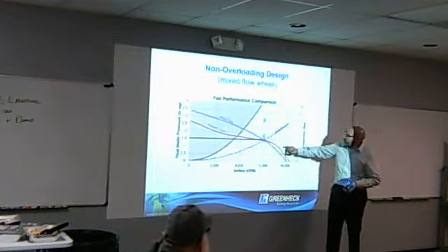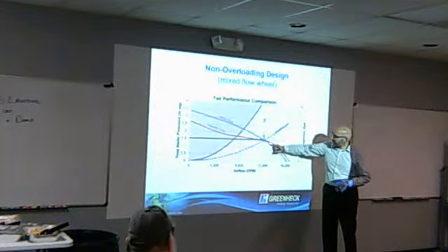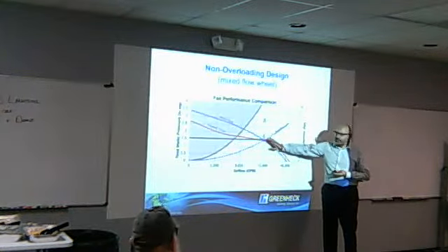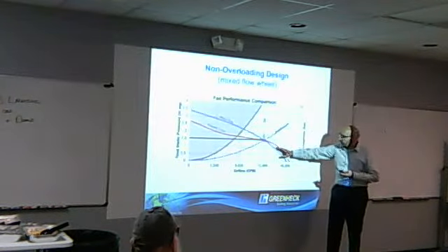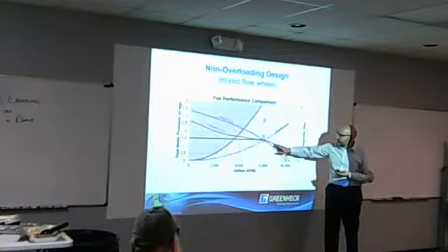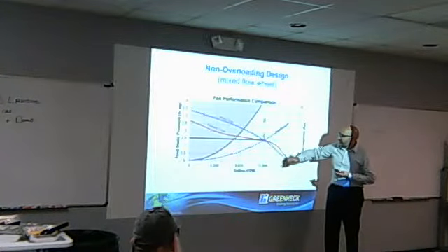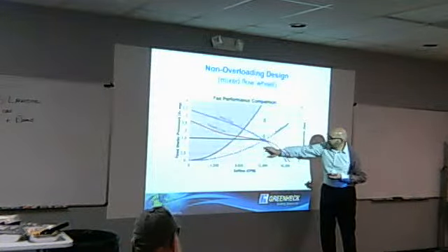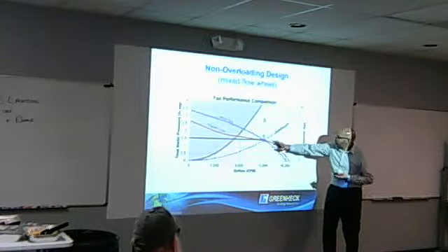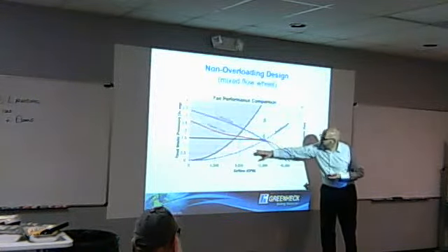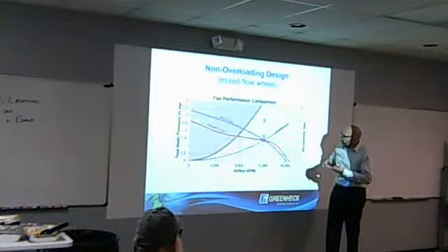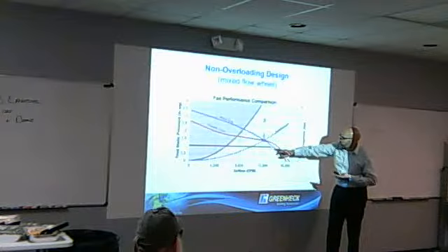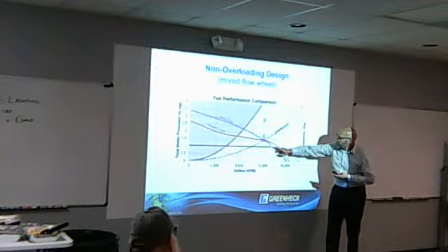So we have less system pressure, and to move this amount of air, we're going to stay on the same RPM curve, but we don't need as much pressure to move 12,000 CFM. That curve ends up coming down here, and you end up coming up through here. You imagine this being parallel coming up through here. So we're going to pick a point out here.